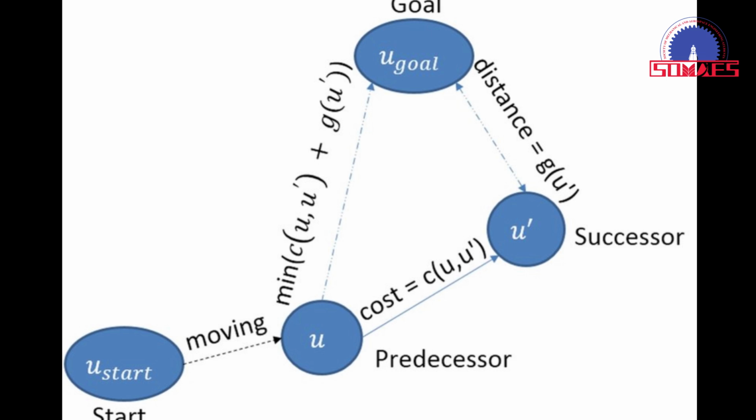Then a real-time update is equipped. D* Lite is equipped with a real-time update. Unlike other algorithms, which solely depend on the first node and the last node, this algorithm can change its path based on the dynamic data it is fed. Let's say that while traversing a path, the robot experiences a hurdle. To avoid this hurdle and again traverse the shortest path, D* Lite works perfectly. So D* Lite is great for helping robots navigate complex areas, adapting to new hazards while staying on the best path.